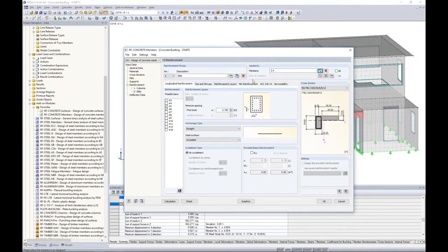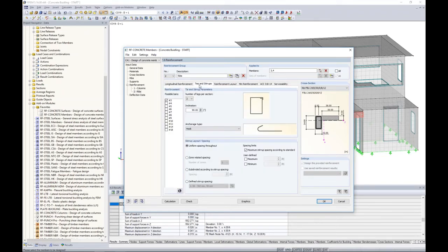And as far as the rest of these tabs, most of this will remain unchanged. For example, the longitudinal reinforcement will still let the program optimize between number 5s or number 6s. The ties, maybe I'd like to increase this to number 4s. I expect to see higher shear here, of course, in comparison to my column, so we'll increase this to number 4s. And let's use different zones. So the program will optimize the spacing in 3 different zones. Areas where we have higher shear will have closer tie spacing. Areas where we have lower shear, of course, will have tie spacing further apart.